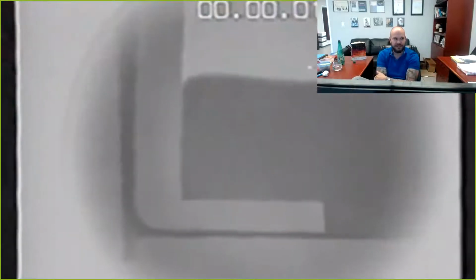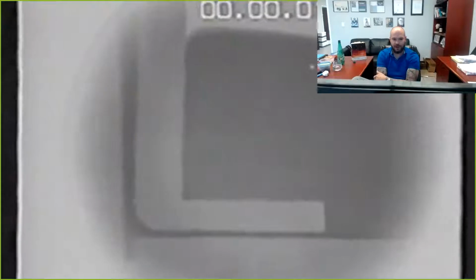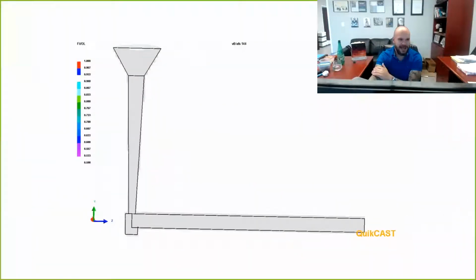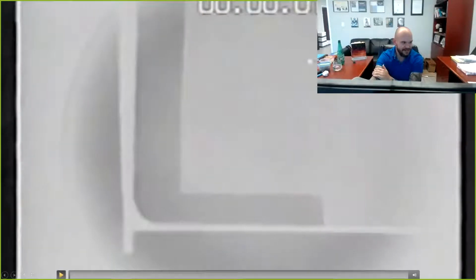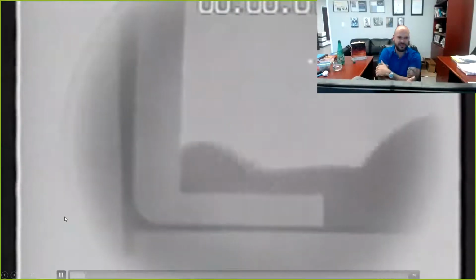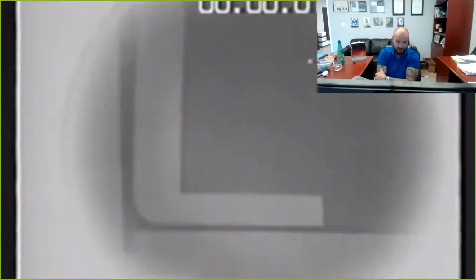Now, this was done by putting the nozzle of the ladle into the mold, so we still didn't take care of the pouring cup problem, and we haven't taken care of the velocity problem as the metal's entering. Because you can see, let me replay that one, that as the metal enters the casting cavity, we've got a whole bunch of surface turbulence and we're rolling metal on metal, so that's a problem. Well, we can get rid of that later, but within the sprue and the runner itself, we've got some success. So this was the beginning. This was 1997.